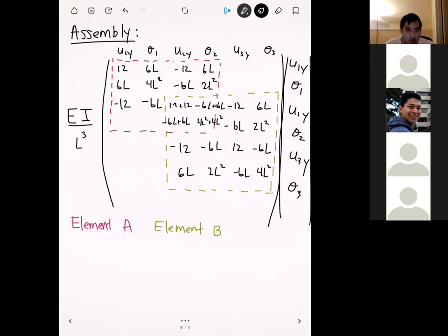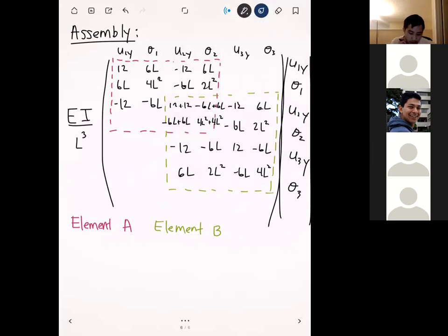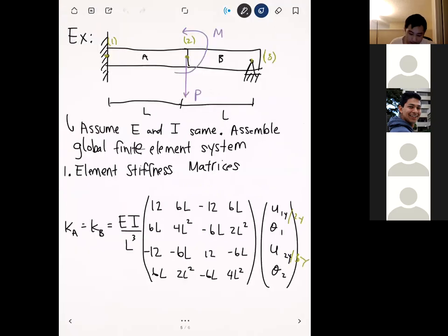But the reason I wanted to do this problem is, part of it was this, but the other part was applying our boundary conditions. And so let's go back to our diagram on the previous page and see where we have to apply our boundary conditions. From the previous page, we see that we have boundary conditions on node 1 here. So what we're going to do is see what type of constraint this is, and then knock out the elements of displacement based on that constraint.